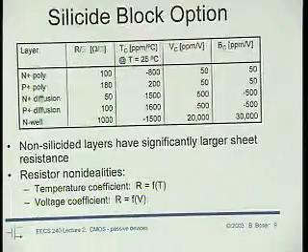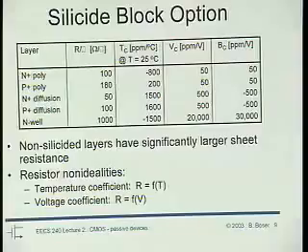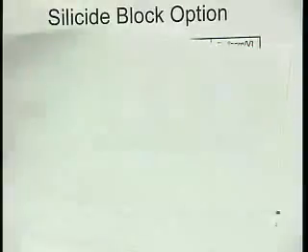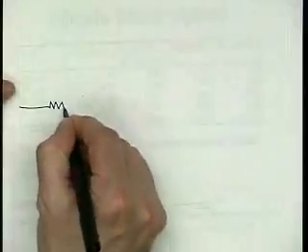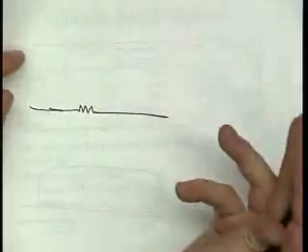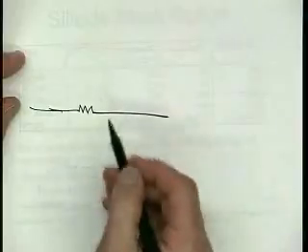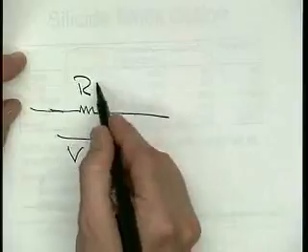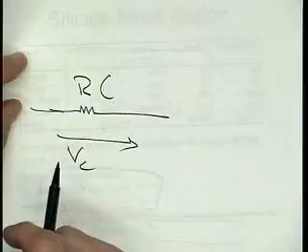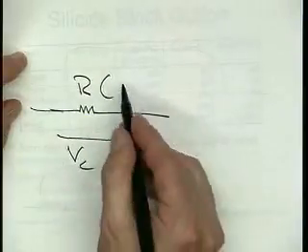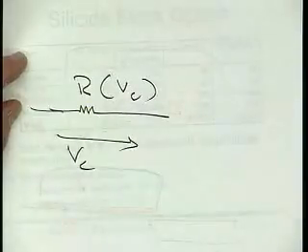In other words, we want to make a 10K or 100K or name it resistor. We wanted that to be that value, but then it changes its value because it gets warm, it gets cold. Heck, can you imagine? It's unbelievable. You take a resistor. What is it for? To run current through, right? So you put the voltage across. The value of this resistor is not only a function of temperature, but it's also a function of the voltage across the resistor.